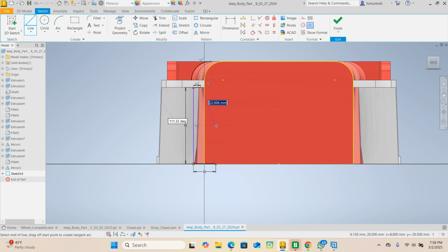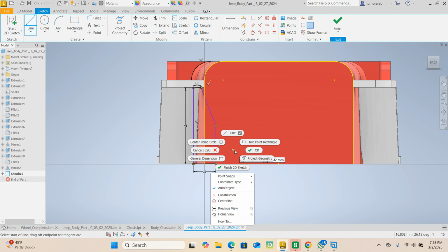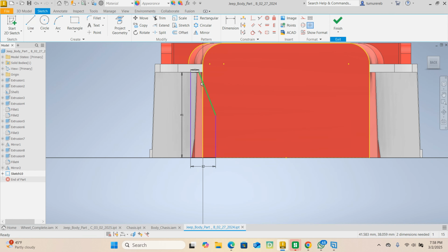So click where you see that dotted line, that's the reference line. Click there and then add your profile there. So we have a profile like this. What shape is this? Trapezoidal maybe? Is it trapezoidal? Alright, so this distance needs to be 25 and why is it not fully constrained? What are we missing? 1, 4, okay.